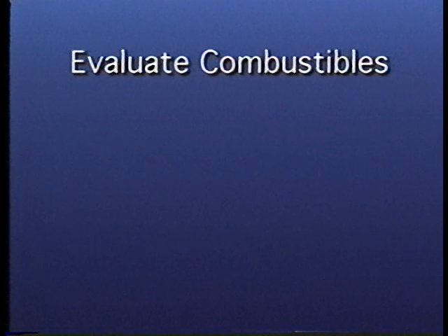In summary, one of the most significant factors in establishing the automatic sprinkler system design is the occupancy hazard classification. You must take care in selecting the classification so that an effective and efficient sprinkler design can be achieved. Unfortunately, you cannot rely solely on the occupancy categories listed in NFPA 13.